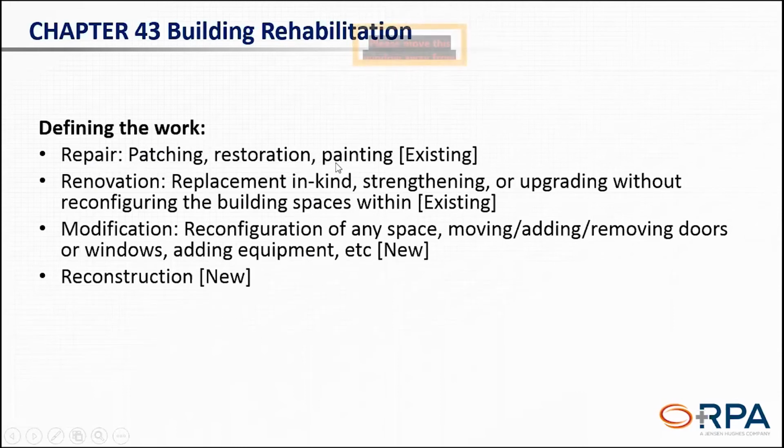So if we're just repairing something, restoring it to its existing condition, then we just have to meet existing requirements. If we're renovating, and that's replacement in kind, or strengthening or upgrading without reconfiguring the actual building, then we can still meet existing requirements. But if we modify or reconstruct, that's where we have to meet new requirements. So if we're changing things, removing, reconfiguring that space, we need to convert and go to the new section of that particular occupancy. And typically we're talking about new healthcare.